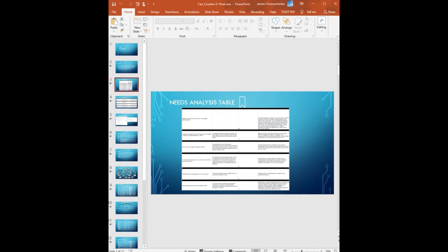Because of the dimensions of the can, the crushing chamber needed to be greater than the largest can size, which was 150 millimeters, and the cross-sectional area or diameter needed to be larger than 65 millimeters. The axle needed to withstand a force greater than the amount of force needed to crush a can, and the casing also needed to withstand that force. A coin mechanism also needed to dispense a coin when a can was detected to be crushed.